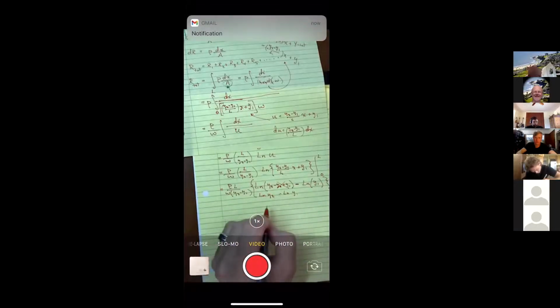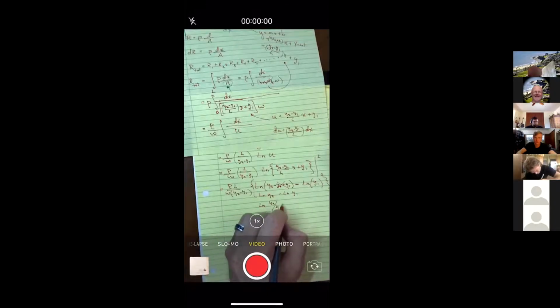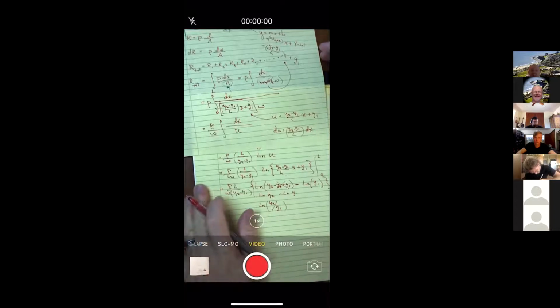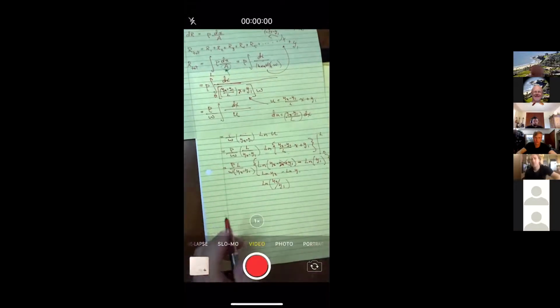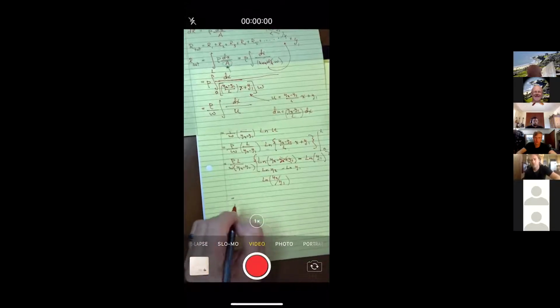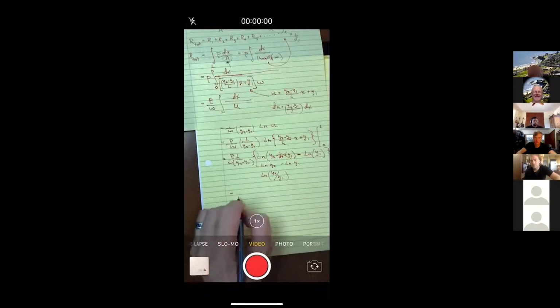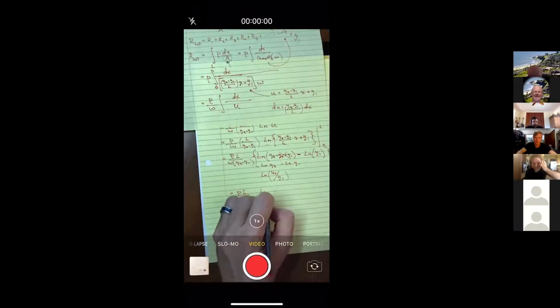And of course, our properties of logarithms say we could take a subtraction and write its mathematical equivalent, which is a quotient. All right, so then I think this would finish the problem by saying that we have the resistivity times the length divided by the width, and then here's the rise of it, y2 minus y1, and then the natural log of y2 over y1. Yay!